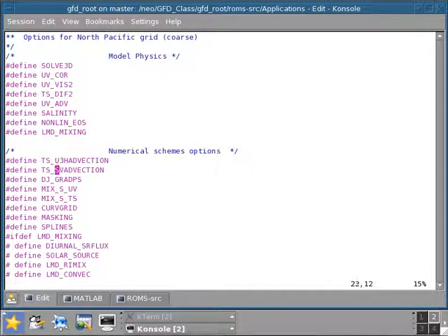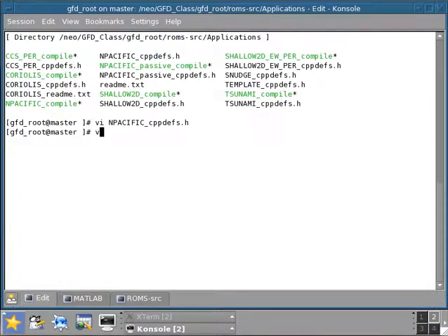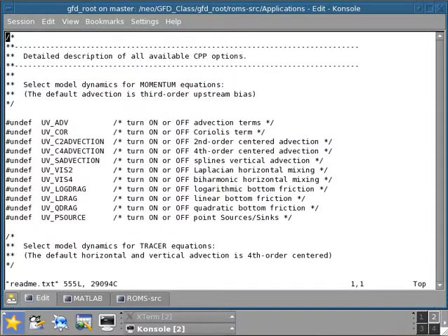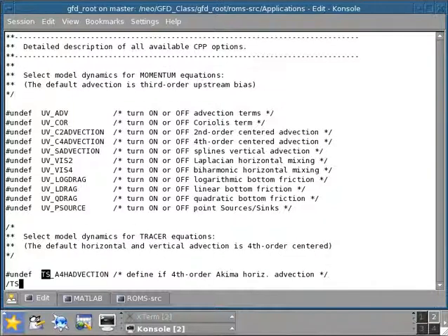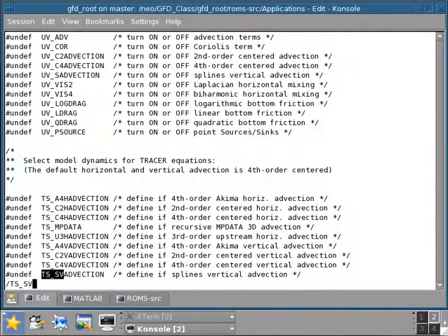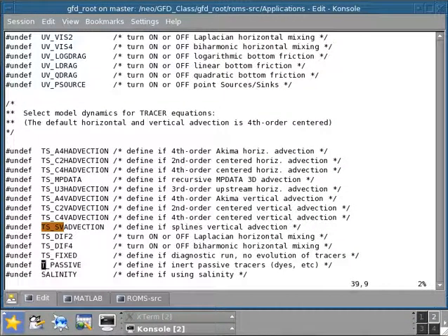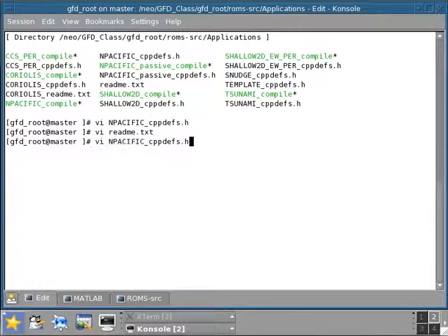We're then going to use a spline vertical advection, so here it's TS_SPLINE, and then V advection stands for spline. And keep in mind that if you are uneasy about what these things are, there's always, for example, your README file where you can find all these different types of available schemes. So this is an example. I just picked some that I typically use myself.